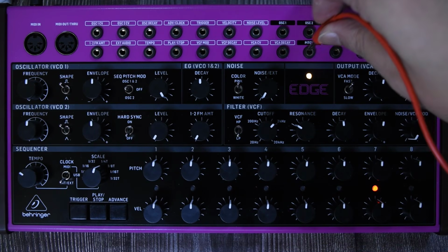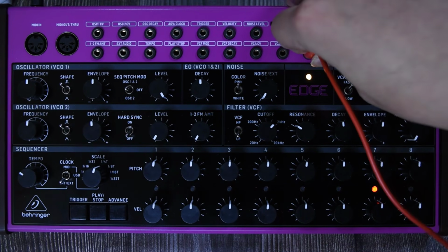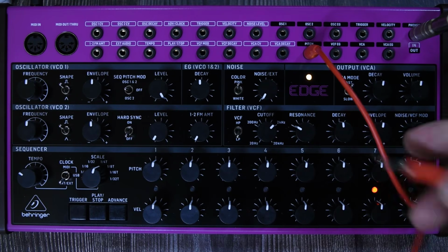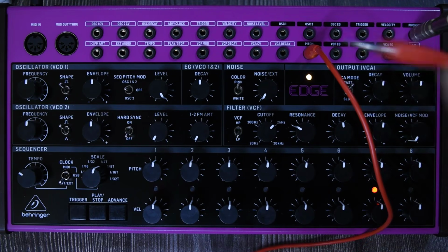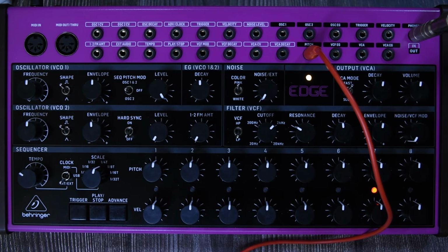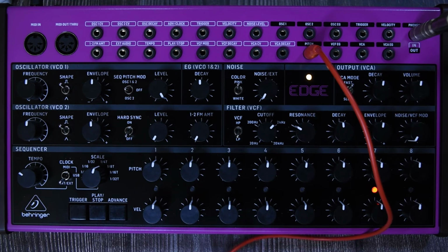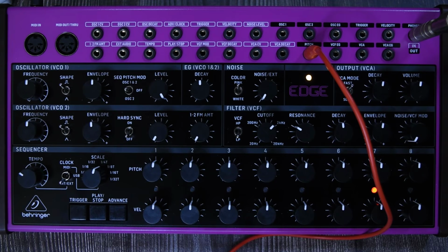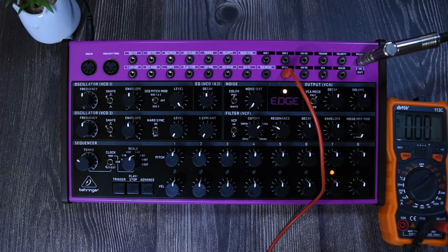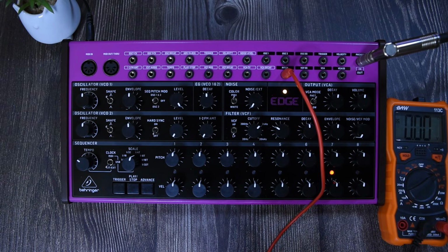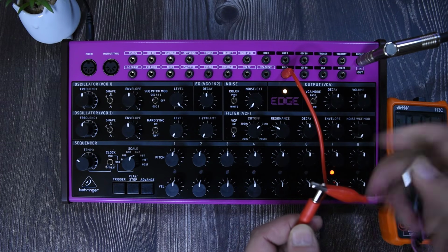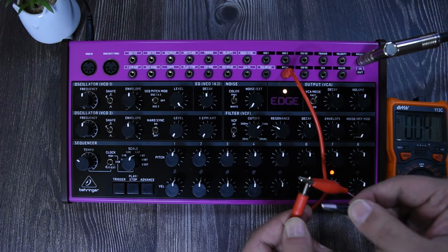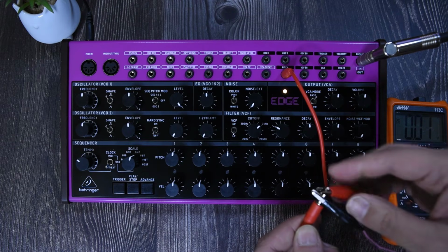So if I connect a cable right here, whatever we connected at the other end is going to receive an output or a voltage. Now the case of the pitch is going to be from -5 to +5 volts. If you have a multimeter, you can check whatever it is that you're doing on the other end. You need to connect the tip to the red and the black to the sleeve, which is round.